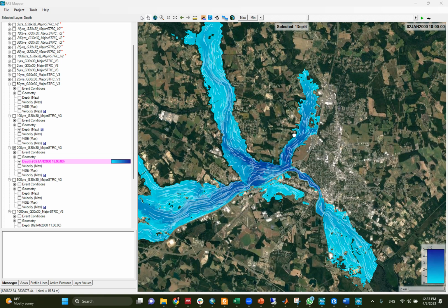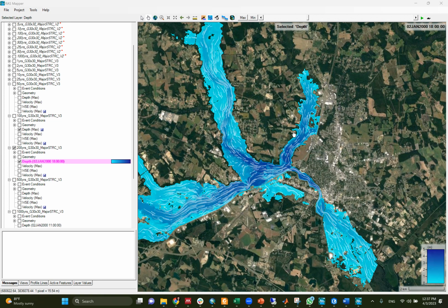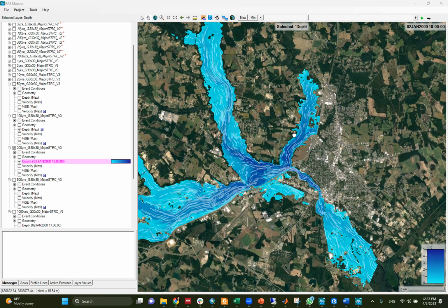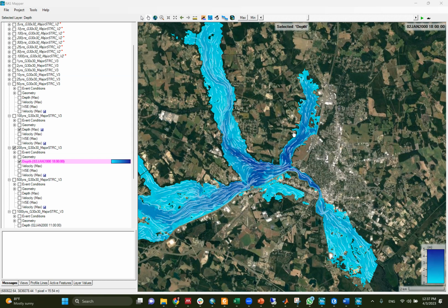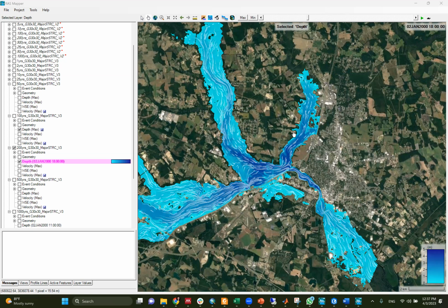The second problem that you will have is, I believe my simulation is a 1 week period, maybe January 1st up to January 7th, right? When you run 7 days, your simulation will end up here and will not cover the whole floodplain. This is because my simulation is very detailed. I include different Manning coefficients, every part of the area has a different Manning coefficient. The Manning coefficient controls how the water flows, how fast it flows.